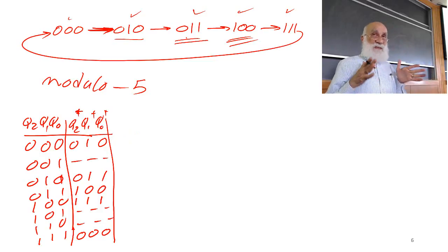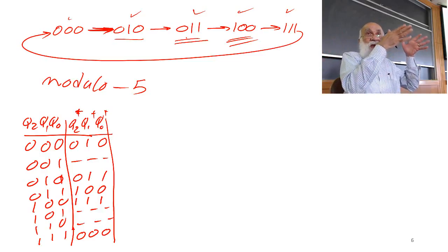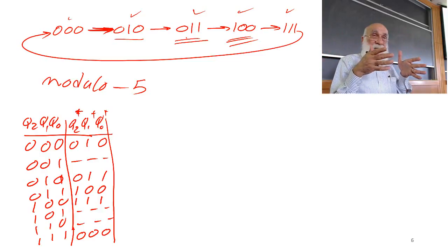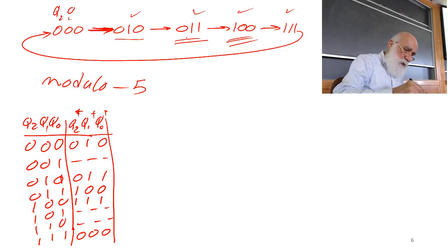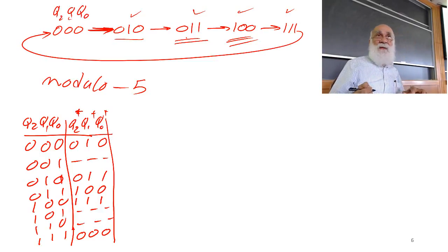When I get to this point where I have a transition table, see, the table I am showing you is a transition table. It's not the truth table. See, truth tables, they don't have timing. They don't have pluses. This is a transition table. It's showing the existing Qs and then the next Qs. This is Q2, Q1, Q0. Present Q and the next Q.